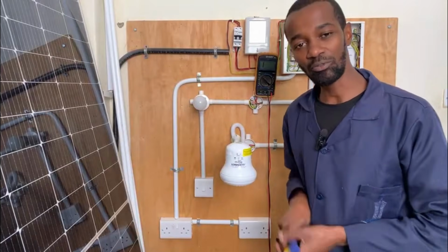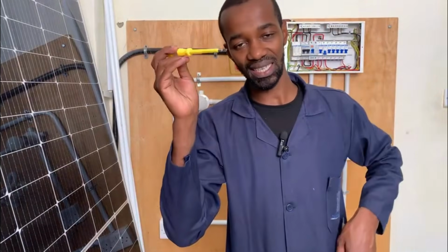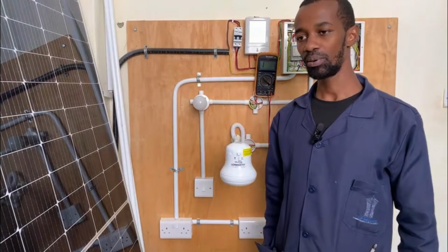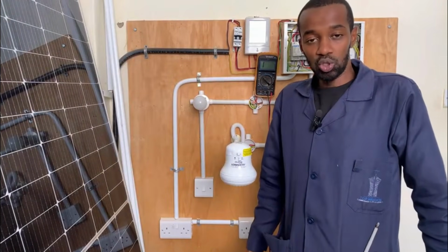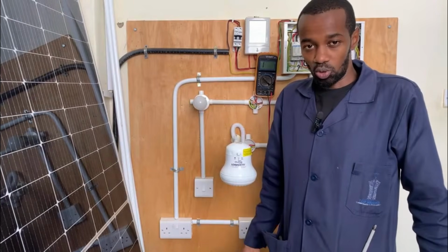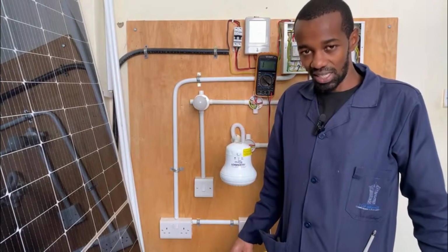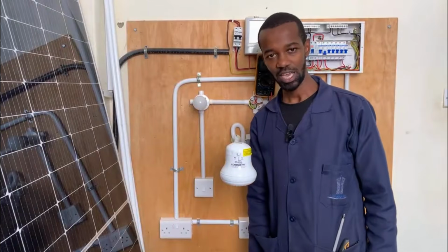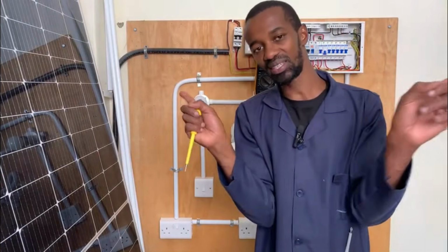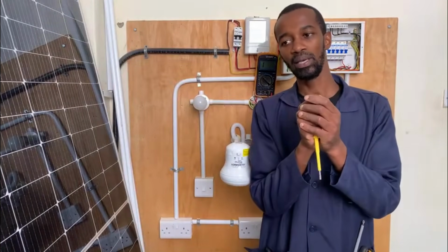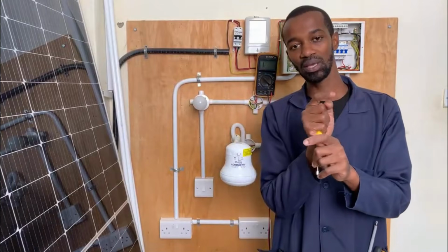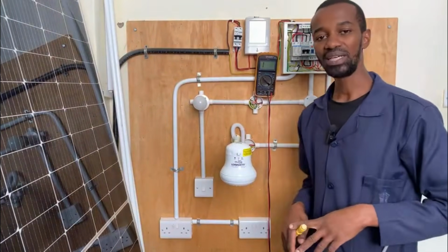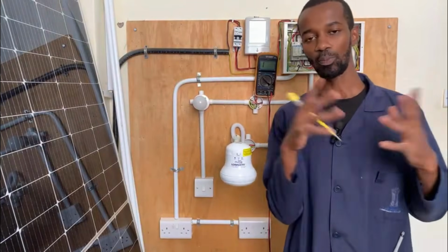My top boss, if you only work with this tester to go and troubleshoot, you'll have a very deep problem right there. Because you'll spend a lot of time on something that would have been sorted out very fast using a digital multimeter, doing continuity tests. If there is an opening in the circuit and you probably have the MCB not tripping, but circuits are not powering.